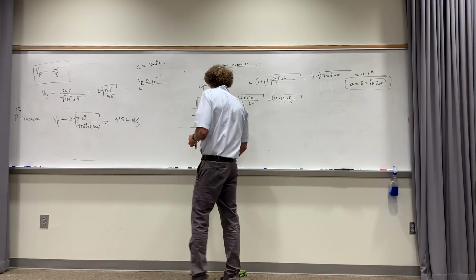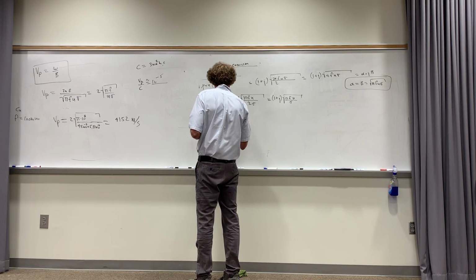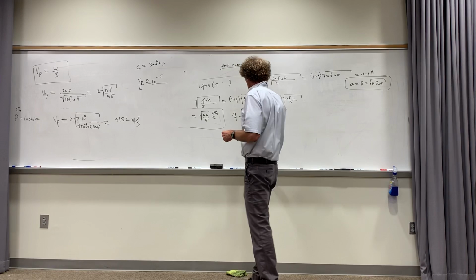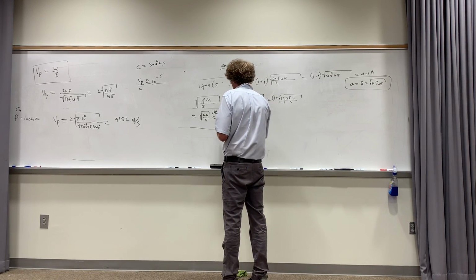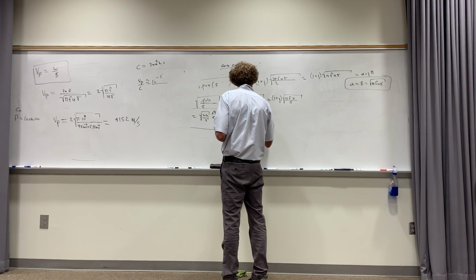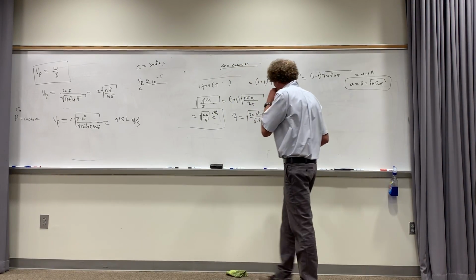The other thing I'm going to do, I didn't do this for this one, but let's calculate the characteristic impedance. So the characteristic impedance for that would be the square root. We know it's at a 45-degree angle, but it's omega, which is 2 pi times 10 to the 8th, times mu, which is really going to be 4 pi times 10 to the minus 7th, right? Over sigma, and that's 5.8 times 10 to the 7th. What do you get for this intrinsic impedance?